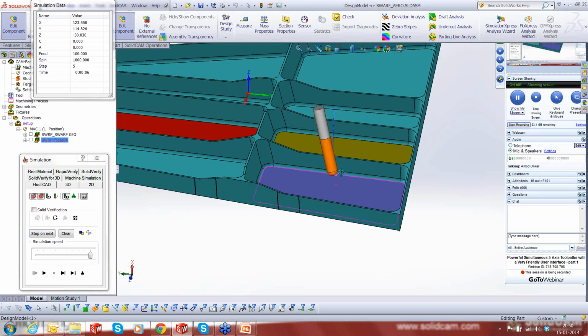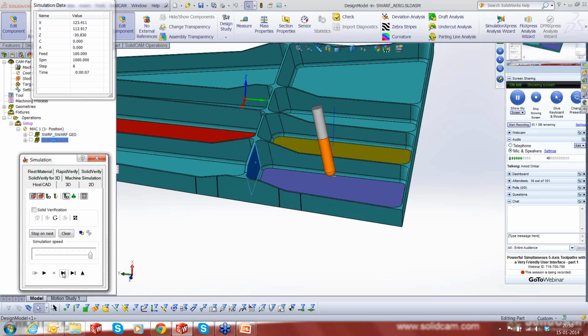same thing, this surface is influencing the lag angle of the tool. Okay, it's done nicely. It's doing nice. Okay, it's now tilting. It's become straight. That's understandable. Okay, now there's something crazy that's happening. The tool is now trying to tilt into another direction. Its lag angle is changing, although it should not, because this wall out here where it is approaching is straight. So actually it has no reason to change its tilt angle.